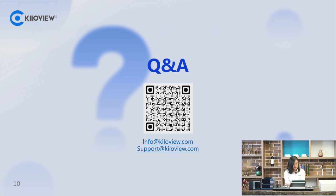What's the latency to expect from a video signal from the camera to the program screen? Will the latency remain the same for all the videos processed through the Kiloview system? With NDI, the end-to-end latency for full NDI is about 80 milliseconds. For the Kiloview system, we are not adding latency, so it would be similar. But of course, it depends on the real network situation.